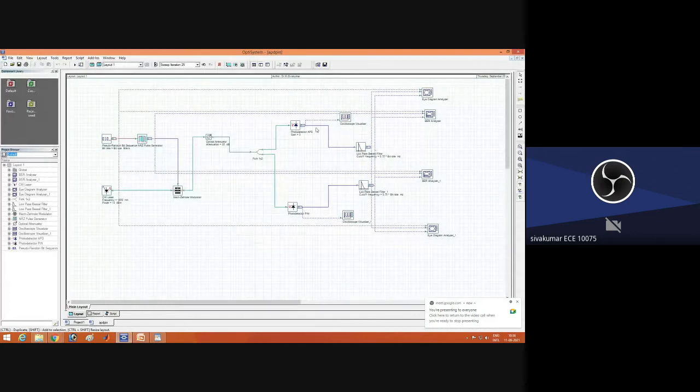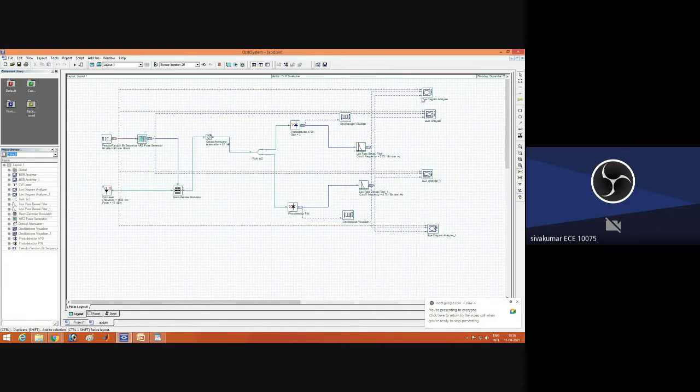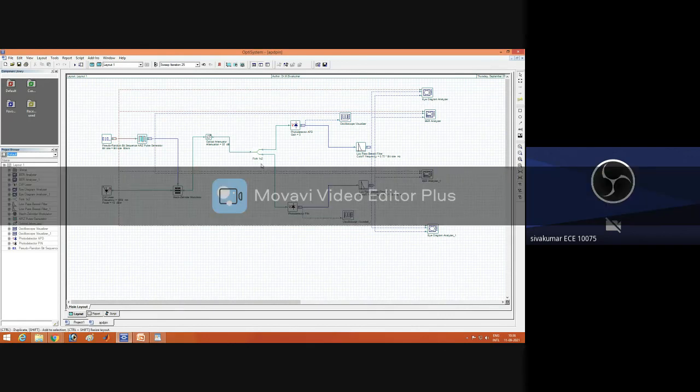Asking for the avalanche photodetector means here no need of this fork. After attenuator, you just connect photodetector. After photodetector, you connect any type of low pass filter, Bessel filter, or Gaussian filter. Here, according to your requirement, you include the subsystem for optical receiver sections. Okay, another question is, for pin photodetector you don't use the fork block.